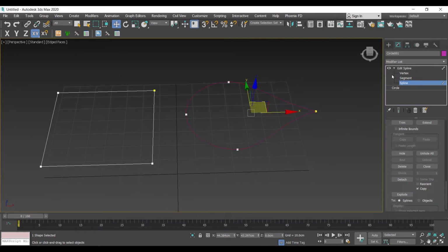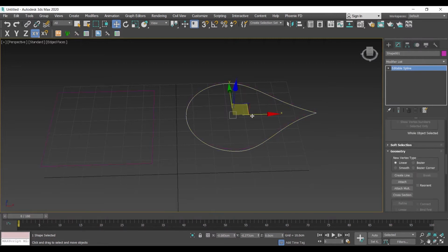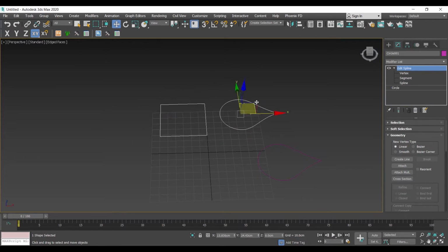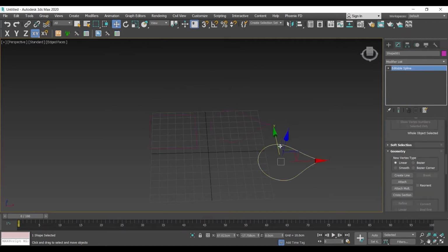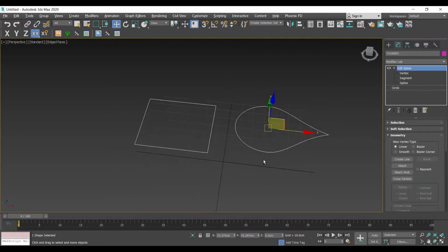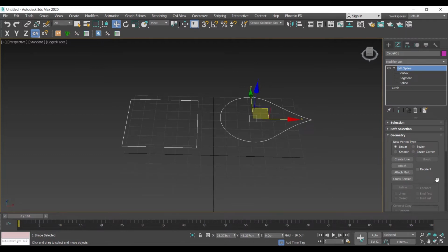And now you will see that I have two lines over here, one which is detached and one which is not. The original one stayed here, and that's the copy. I detached it and made a copy of it. Same thing as the polygon options. Great. That's one of the main things that you're going to use, Detach and Attach.